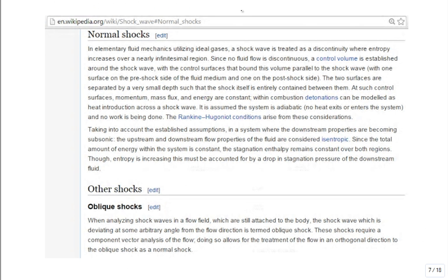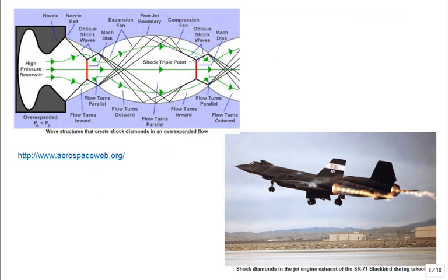Okay, what about these shocks? There's more you can read about them, but they're a discontinuity in the entropy. It's a highly irreversible zone that's modeled as being just a planar surface. It can have curve to it, or it can be a normal shock, which is flat, or oblique shocks are different shapes. Here is just a quick look at high pressure.